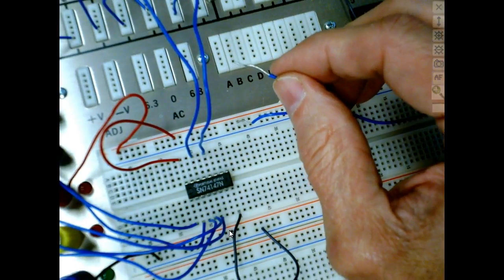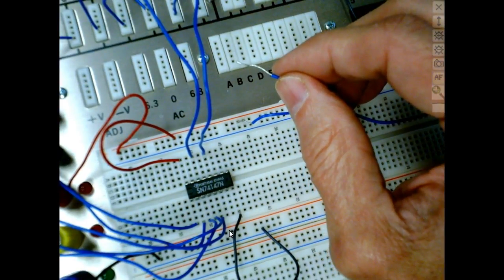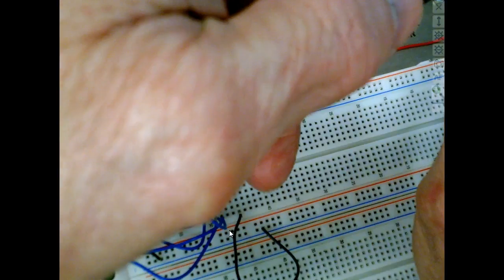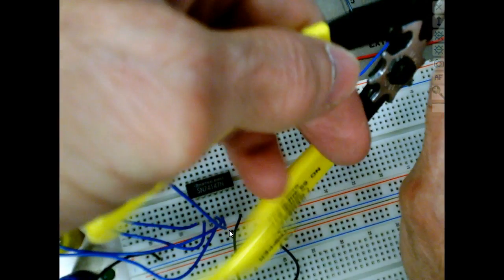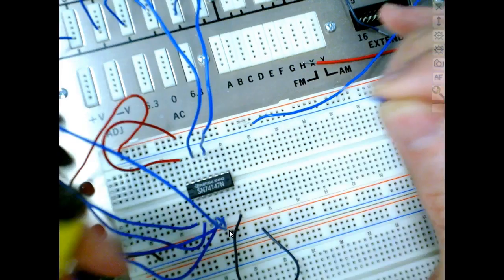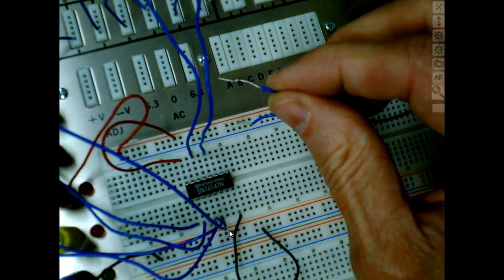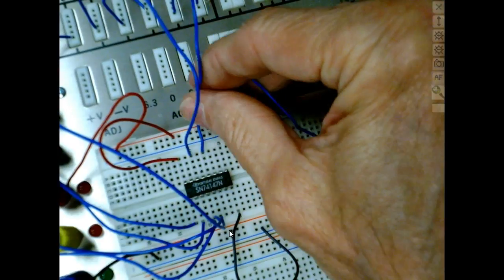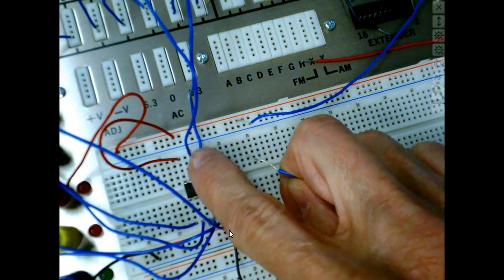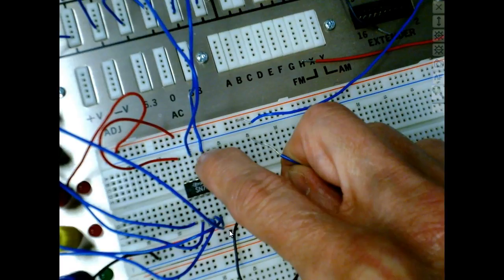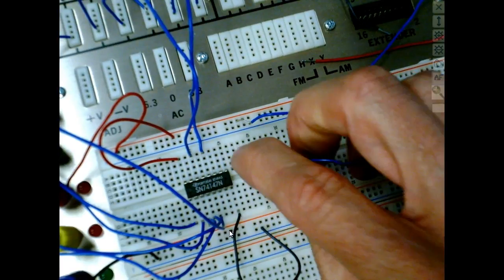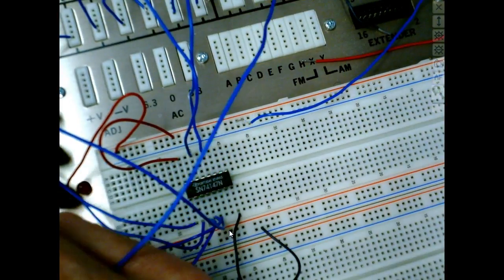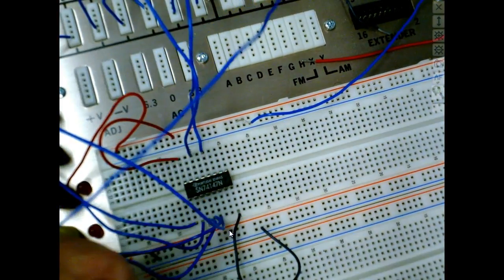We'll double check this. So it looks like I might have hooked up some things wrong. By the way, when you strip these wires, you don't want to strip them this long. What you'd like to do in digital is that when you insert these things, your insulation is almost right into the board. Because if you get a bunch of bare wires sticking up there while you're hooking up all this circuit, it's going to be impossible to keep them from shorting out. So undoubtedly we use this thing here for something else.